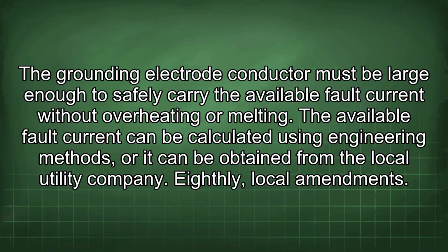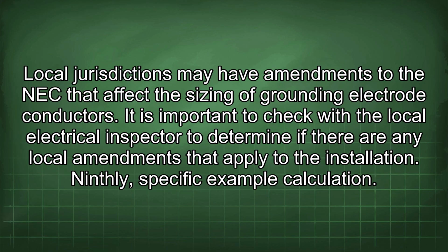Eighthly, local amendments. Local jurisdictions may have amendments to the NEC that affect the sizing of grounding electrode conductors. It is important to check with the local electrical inspector to determine if there are any local amendments that apply to the installation. Ninthly, specific example calculation.